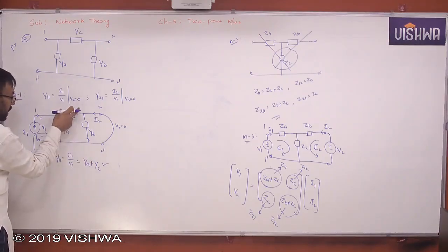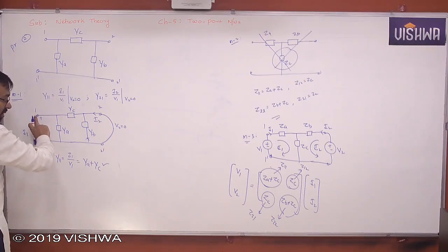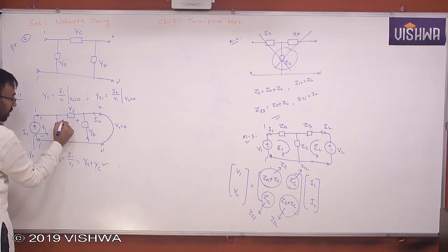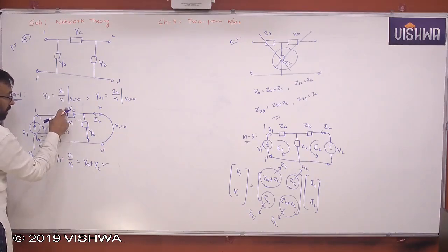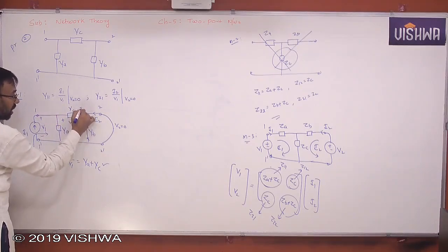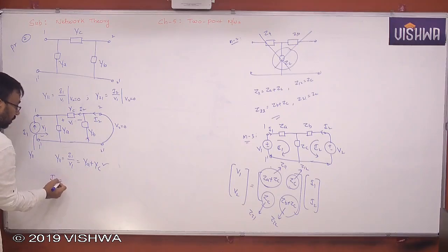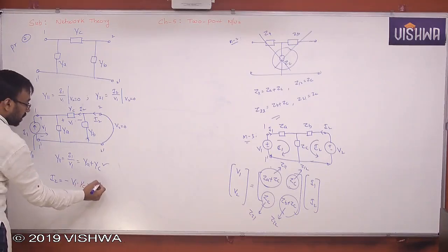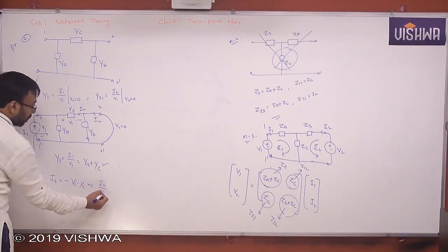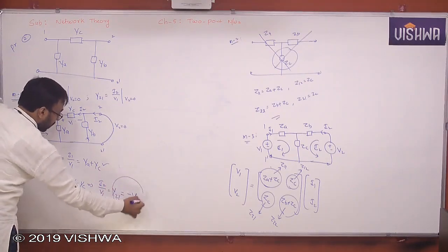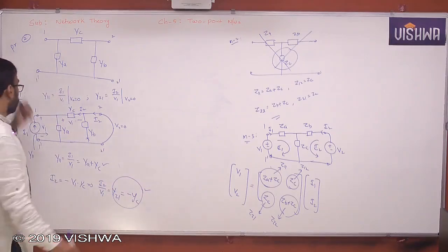Can I find the same current in terms of V1? Because V1 is the voltage across this, the same voltage will appear here also. So what is the voltage across this? Plus minus V1. So V1 into YC will be the current flowing here in this direction. But I2 will be the current flowing here in the opposite direction, because I2 is flowing here like this. So I can equate now I2 is equal to minus V1 into YC. From this, I2 by V1, which is nothing but Y21, is equal to minus YC. This is very, very important. Clear all of you, okay?